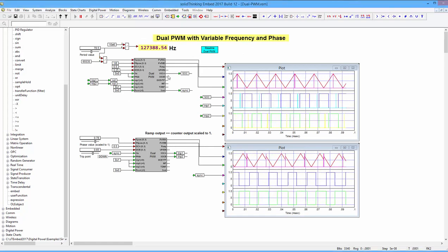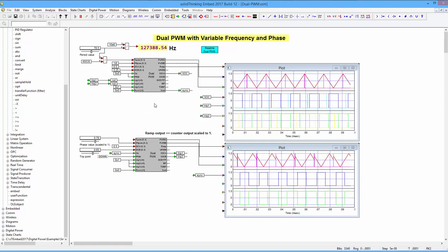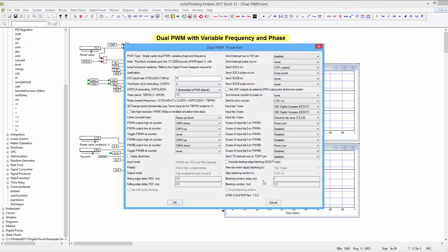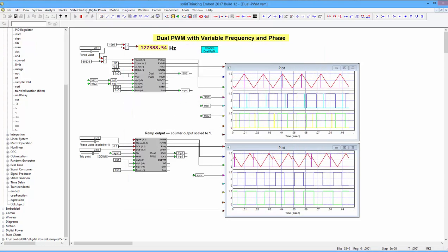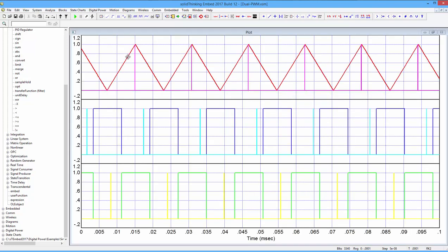Here we're simulating the digital PWM, the actual peripheral inside the C2000 microcontroller. It's a type 1 peripheral. We can even stop the simulation. So when we have the up down count here, this is our trigger. For example, for the start of conversion, we can trigger it on the period. If we switch on here, as we're doing, we're switching on the down count, we're switching off on the up count, and the inverse for the other PWM.